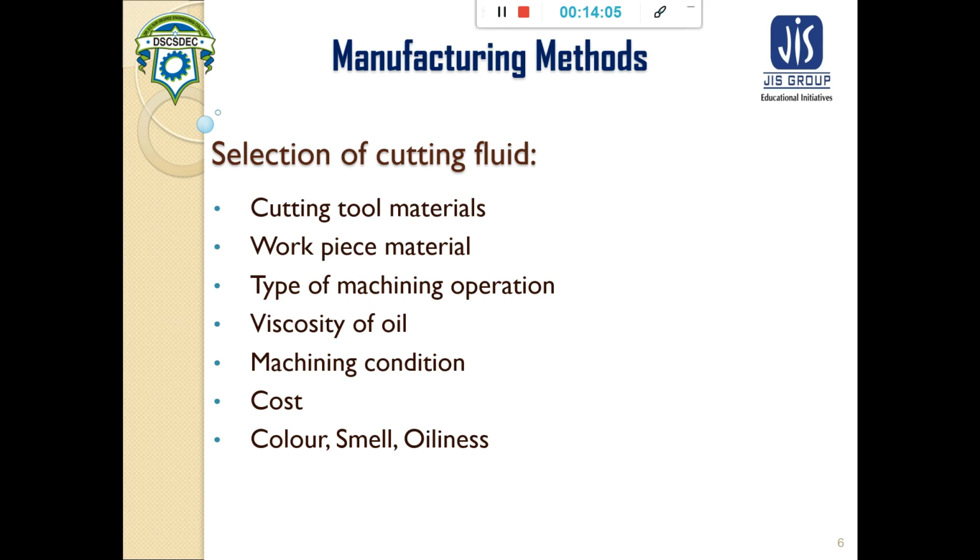So this combination, HSS with soluble oil, or carbide insert with synthetic oil, depends on the cutting tool material. So the selection of the cutting fluid depends on the cutting tool material first.